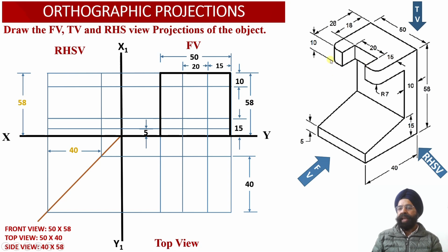And now we know that corresponding to this top face, we are going to have a horizontal web at the top surface, carrying a rectangular slot at the center of this horizontal web. So this horizontal surface will be visible to the observer over here. This is the base of this horizontal web which is lying at the top surface of the solid. So this base will be visible to the observer. Now we can check that there are three segments which will be visible to the observer as the observer is going to look at the solid from the front side.